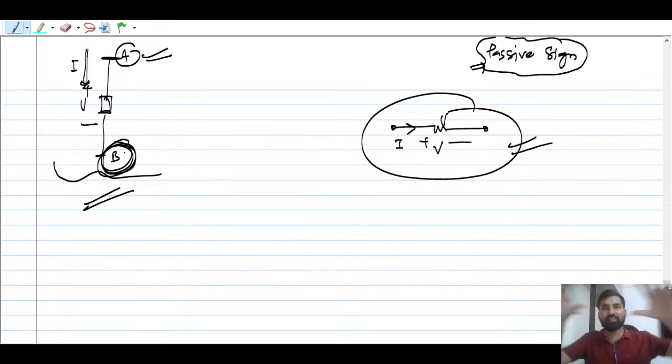Whenever you see any circuit, we have to always consider one reference, you need to take one reference. Many people forget this. Whenever they apply KCL, they forget the reference point. You never have to forget the reference point. So always take it, so that you can say point A has higher potential if you compare with point B. In case of analog circuits also, when you talk about BJT, bipolar junction transistor, supply is here.